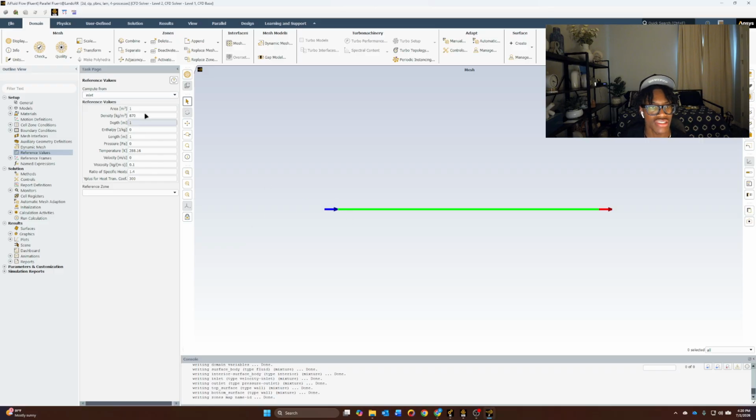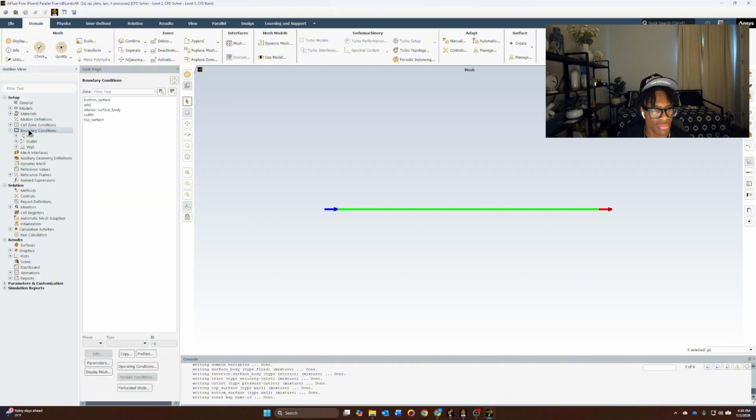What you want to make sure is that if you're creating a new fluid or editing the values of that fluid, the density you plugged in is here and the viscosity is here. I'll get into it in a second for the boundary conditions, but you just want to make sure that's there. If it's not showing, even though you updated it in the fluid, you can open up another area on the pipe and then go back to it, and it should update and refresh. I'll show you what that looks like now, because we're going back into the boundary conditions.